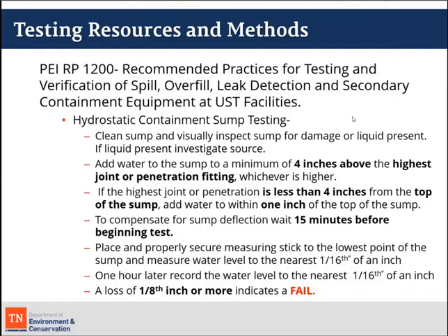You'll want to properly place and secure a measuring stick to the lowest point of the sump and measure the water level to the nearest 1/16 of an inch. So PEI says that you're leaving that measuring stick in the sump, secure, for the length of the test.